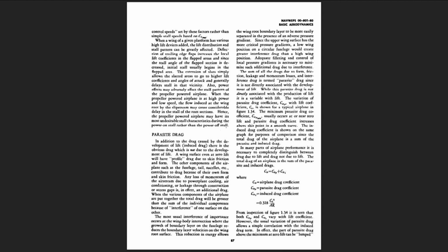CD = CDp + CDi, where CD = airplane drag coefficient, CDp = parasite drag coefficient, and CDi = induced drag coefficient, or CDi = 0.318 CL² / AR. From inspection of Figure 1.34, it is seen that both CDp and CDi vary with lift coefficient.